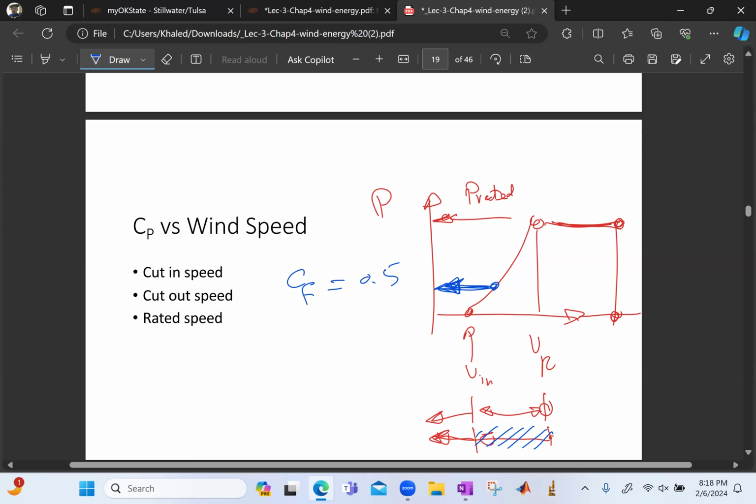Yes, so if I ask you to specify for a place where they really want to have 10 megawatt all year long, and that place has a 0.5 capacity factor, you can notice that it's not just the site that's responsible for that CF. It's the matching between the two of them. Like you are good by yourself, your partner is good by themselves, but both of you together, you are a horrible family.